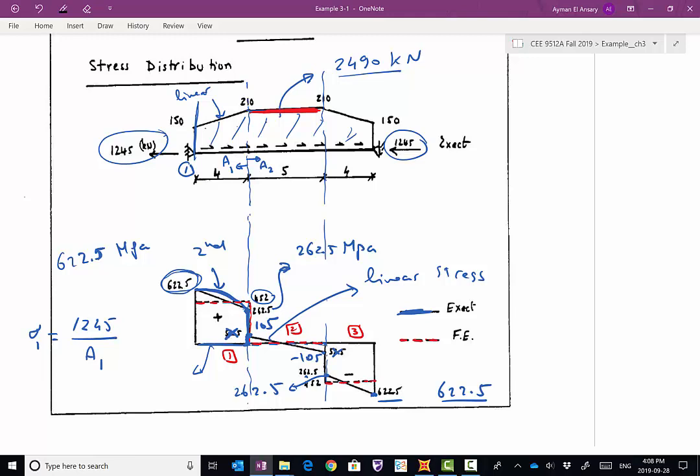Actually, we have a 3D frame element, which we have to limit the number of degrees of freedom in the nodes to reduce it, or we can say that we reduce the element from being a 3D frame element to a bar element, a one-dimensional element. So in SAP, when we model this problem using 3 elements, you will find that SAP right away captures the exact solution. You don't need high divisions because it's a higher order element and we are reducing the number of degrees of freedom.